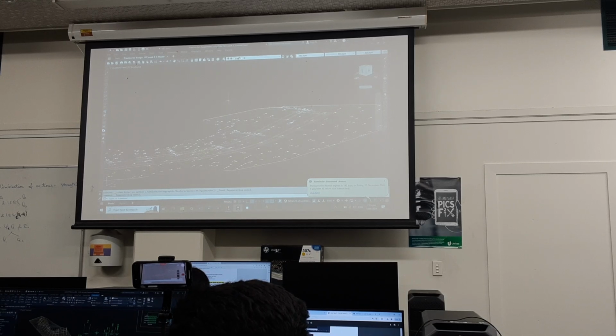One thing I noticed in week 1 was some people imported the data with the coordinates reversed, so the eastings were in the northern column and the northings were in the eastern column. So it should be P, N, E, Z, D. Just point code. Just look at the raw data. You'll see it's point, and then you've got the northing, easting, elevation or Z, and description. So just make sure it's coming in the correct order.